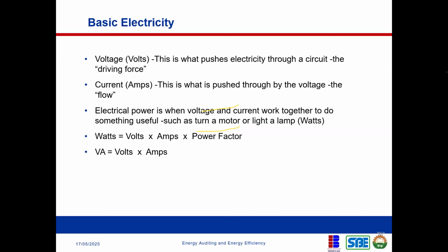So let's move forward. Watts can also be defined as VA, voltage times current. In some instances you might see, for these smaller size inverters, maybe 500 or 1000 VA. So it tells you the power, or the capacity, of that inverter or whatever it is, especially generators. A generator is in kVA. kVA means that you're dividing by 1000. It tells you the power capacity of that generator, right?